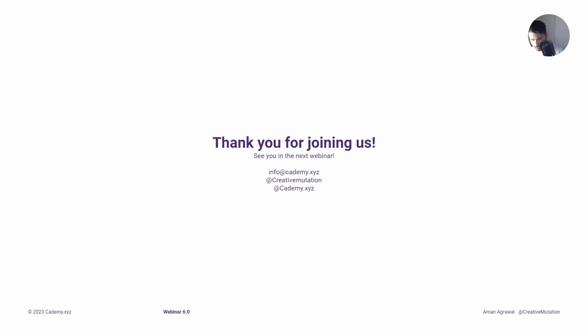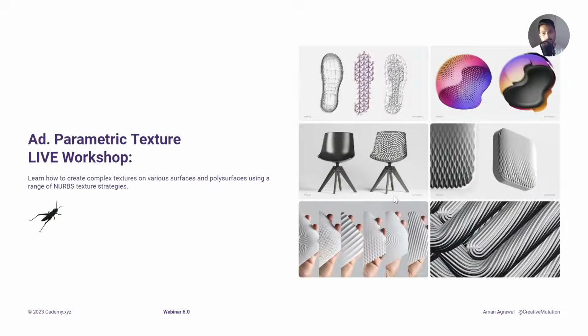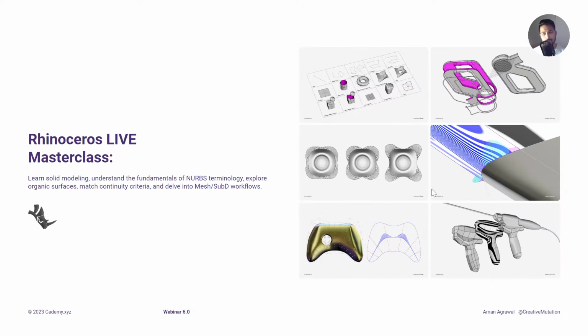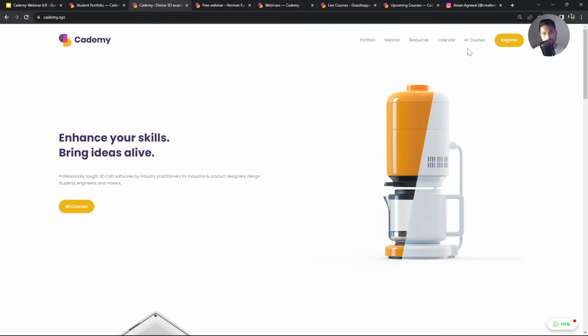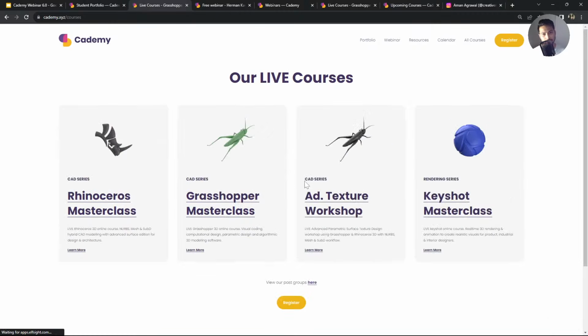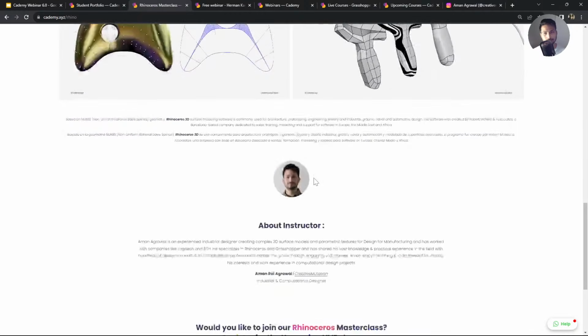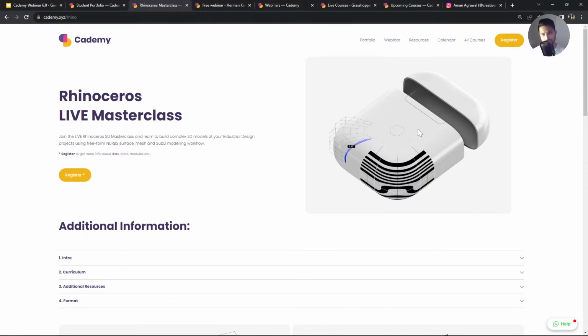Thank you all. Someone asked about a class A surface course on Rhino. We haven't created the class A surface course yet. In the Rhino Masterclass, we do talk about the initial steps that you require for class A surface modeling. You will be learning how to model this AirPod case using the class A surface workflow: single span, splitting as little as possible, matching the surface edge continuity, etc.